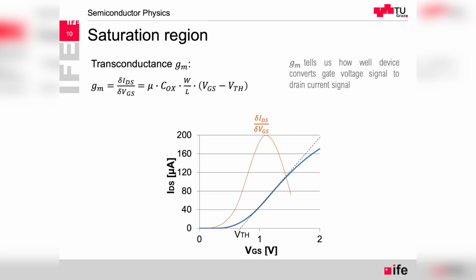That means the current as a function of gate to source voltage. So we see that the threshold voltage is at some point where, below the threshold voltage, the current still is flowing. Then as we increase the gate to source voltage, the current doesn't only keep increasing, it flattens out. And we were also discussing the reasons why that happens, because of the saturation of mobility of the charge carriers, and because of the electric field, the scattering effect, so the mobility is not the same value anymore.